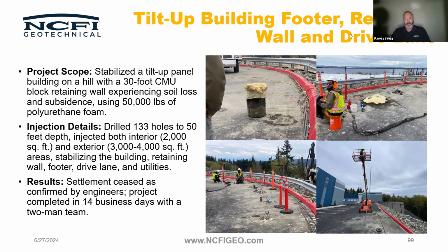The foam is an insulating entity, so R-value around 7 per inch. If we get a hot core inside there, it can cause that hot core to degrade the foam some. And in worst cases, if it has access to oxygen, occasionally it can cause things to smolder around it, or even have a fire.